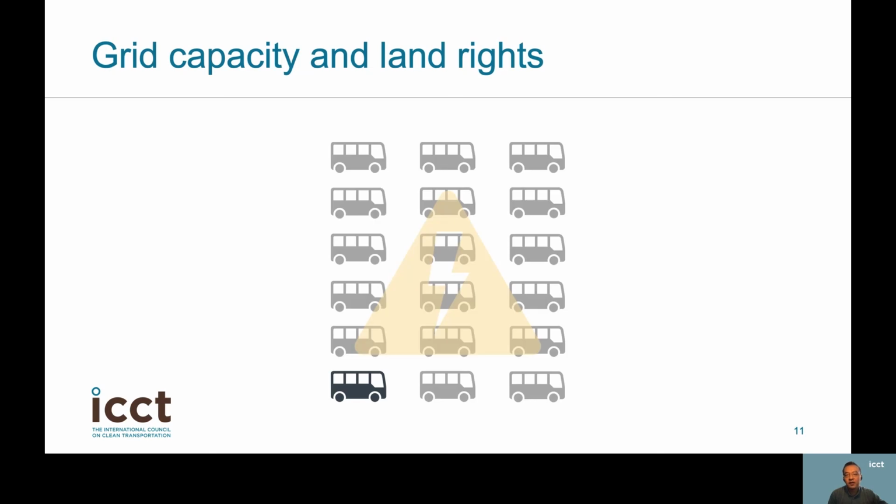At the same time, if the buses are charging at 100 kilowatts each without a smart charging arrangement, the power demand would be at least 10 megawatts, which will likely require power distribution upgrades for existing facilities. This is on top of electricity consumption at the bus depot or maintenance facilities. If the combined electricity demand happens during peak demand hours, the energy costs will increase. This level of power puts operators in a different customer class and requires specialized service and connection to the substation.